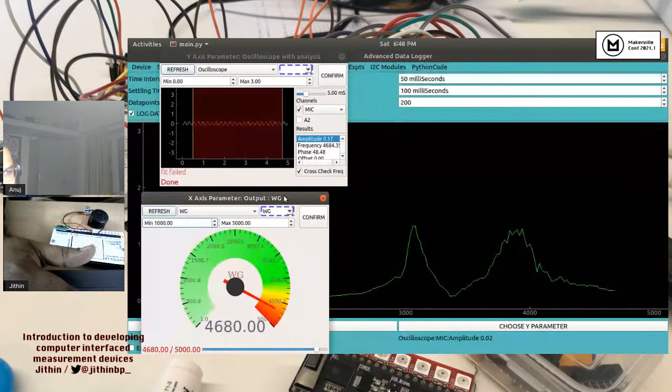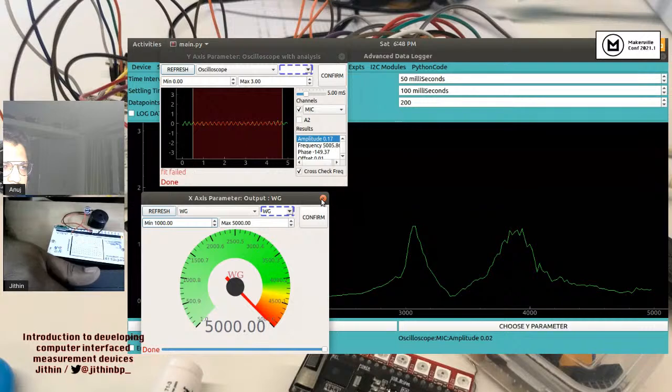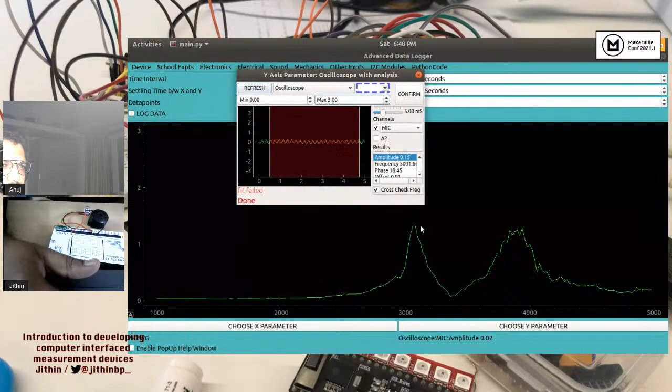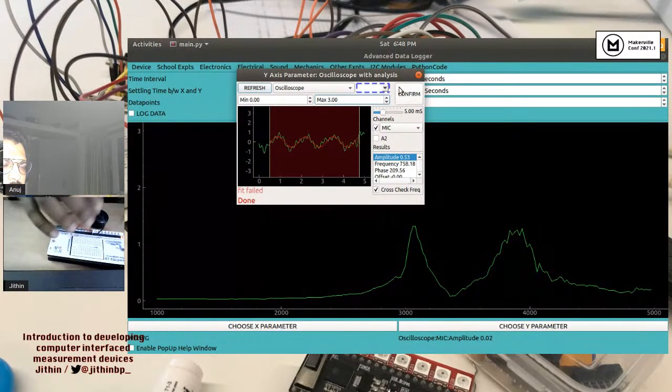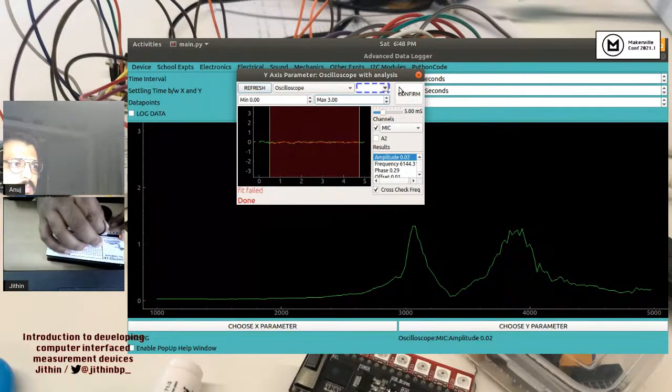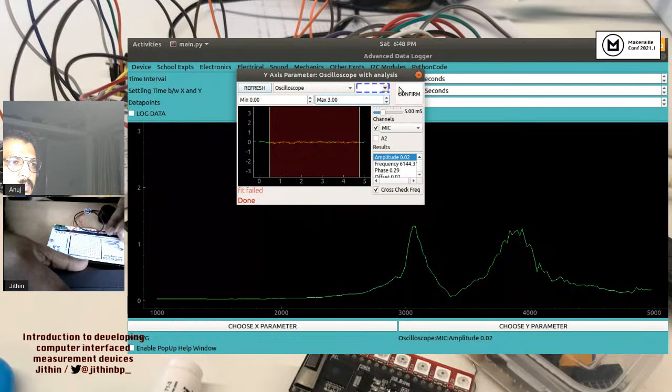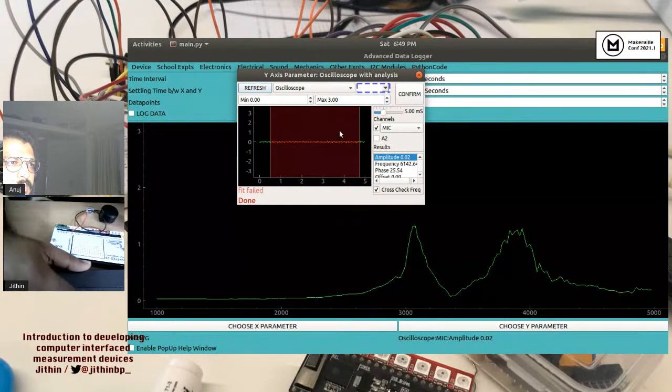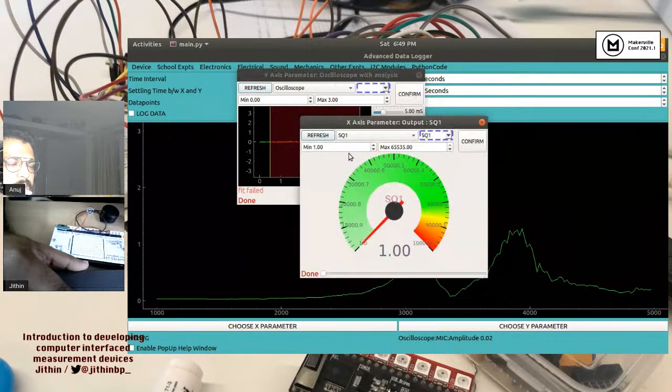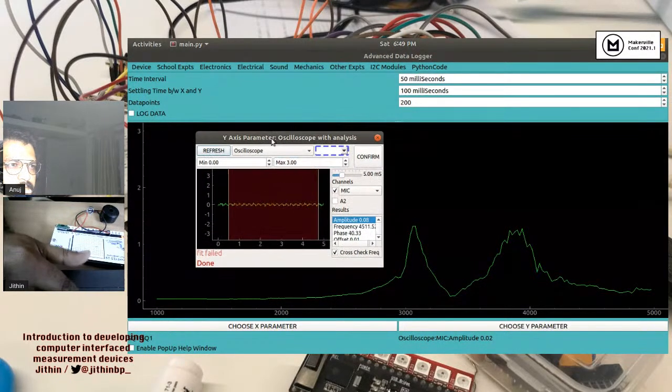Yes. So what we can observe here is that this has two resonances. It's loudest at 3000 something, and it's also equally loudest at 4000 some hertz. Okay, now instead of using a sine wave, if I use a square wave, what is the expected behavior? Right, my X parameter is going to be square, SQ2, the square wave generator. Again, all the way to 5000 hertz only, from let's say 100 hertz this time. Let me just take the data and then we'll explain it.